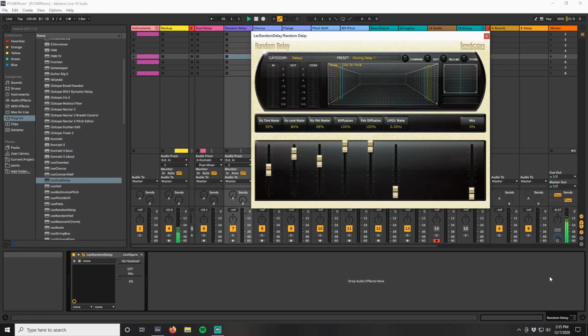The random delay algorithm has 4 total delay voices consisting of 2 delay voices per input channel. Each voice has independently adjustable delay time of up to 9.5 seconds, selectable LFO, and independent output and feedback control. Each of the delay voices' output and feedback paths include an independently selectable filter, adjustable filter frequency, filter bandwidth, filter shelf, polarity, level, and pan control.